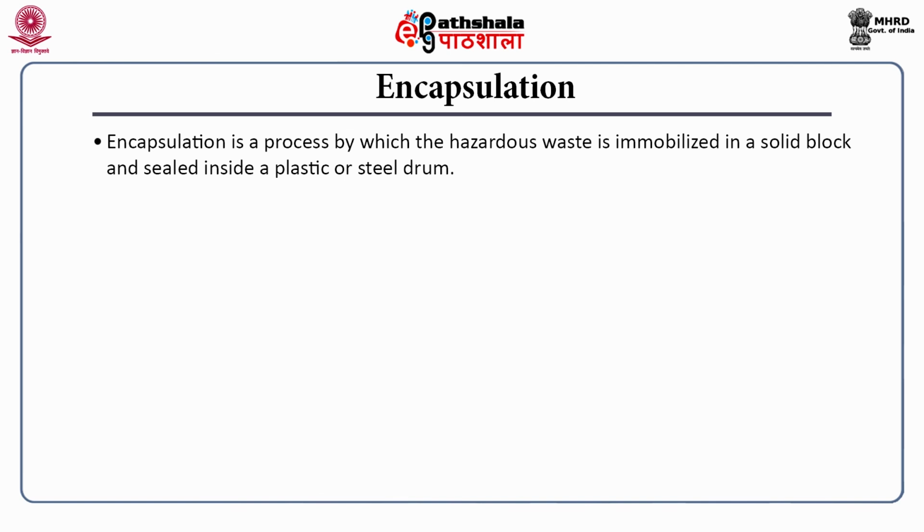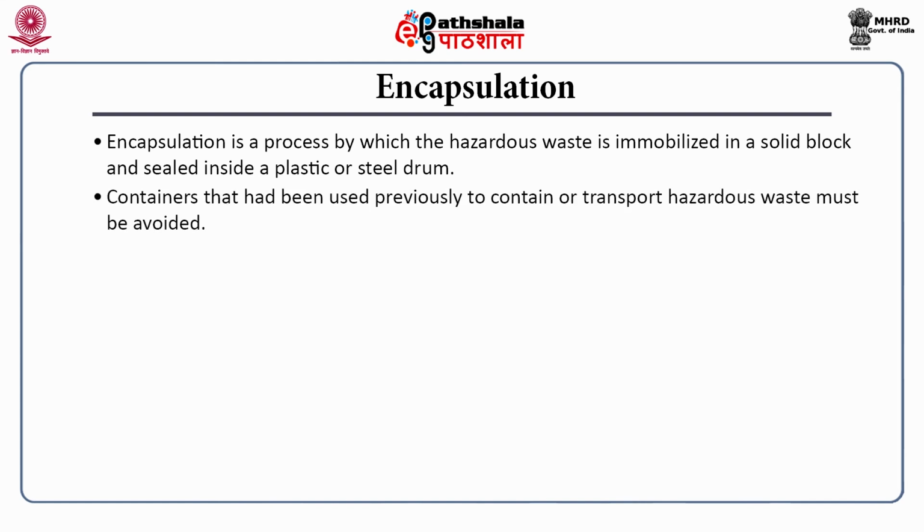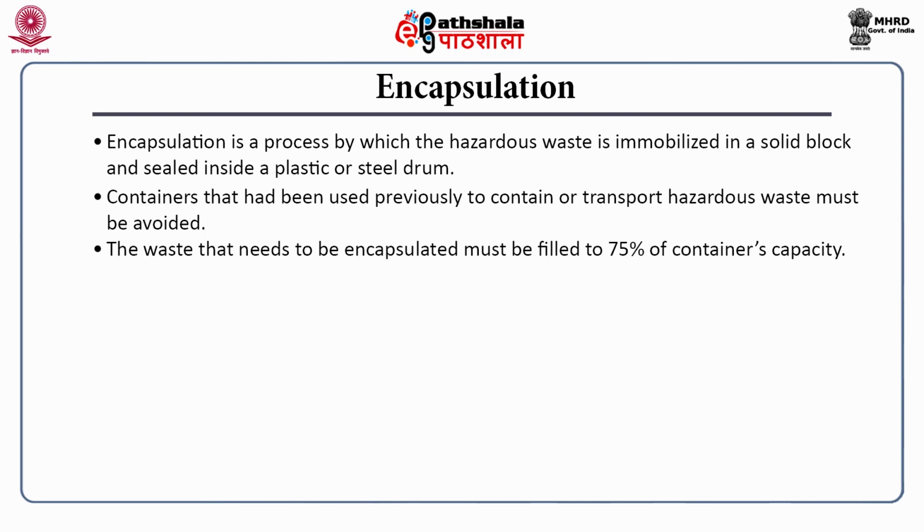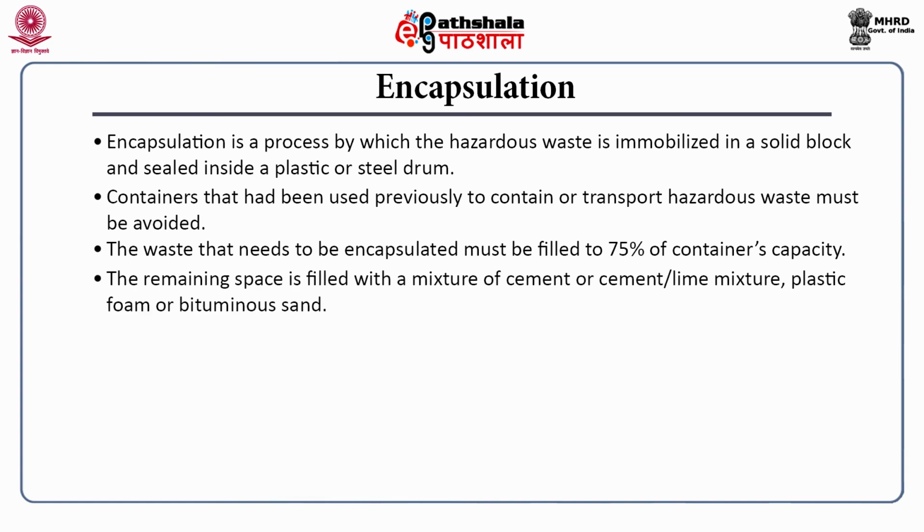Encapsulation is a process by which hazardous waste is immobilized in a solid block and sealed inside plastic or steel drum. The containers should be cleaned previously. Containers that had been used previously to contain or transport hazardous waste must be avoided. The waste that needs to be encapsulated must be filled to 75% of the container's capacity. The remaining space is filled with a mixture of cement or cement lime mixture, plastic foam or bituminous sand.